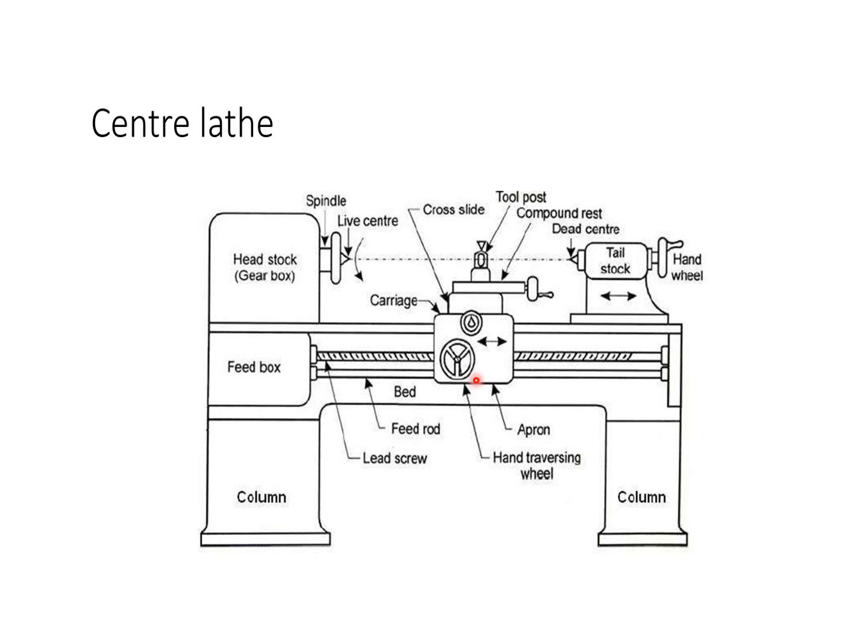Next, feed mechanism. So the movement of the tool relative to workpiece is feed. The lathe tool can be given three types of feed, namely longitudinal, cross and angular feed. When the tool moves parallel to the axis of lathe, the movement is called longitudinal feed. This is achieved by moving the carriage.